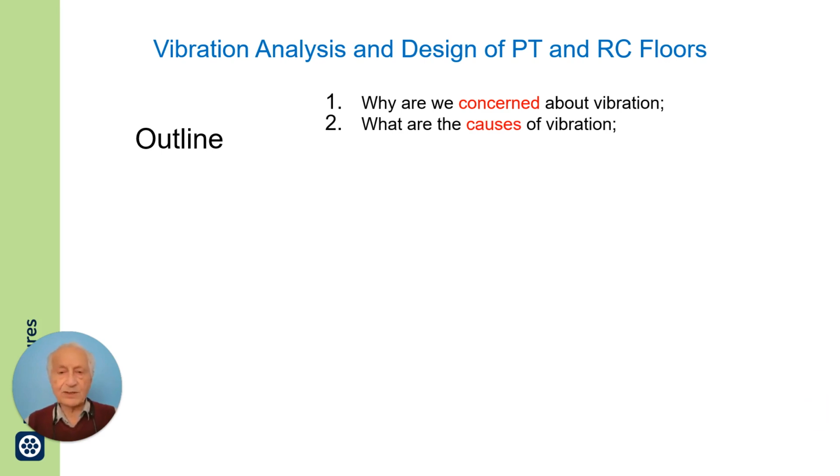Specifically, when it comes to post-tensioning, I jump ahead here and say post-tensioned slabs are typically thinner than their equivalent RC slabs, and that makes them more prone to vibration. That is one thing. And secondly, the advent of computer programs in analysis and design has enabled a lot of architects to come up with larger spans, irregular layouts, aspirational geometries, which at times make them more prone to vibration. For that reason, and for the other reasons that I will be explaining, the vibration analysis becomes more important.